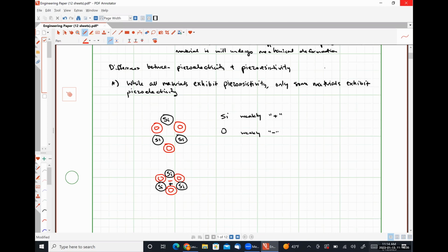Well, what happens when we have separation of charge? It creates an electric field, right? Which is exactly what we would expect in a piezoelectric material. Mechanical deformation results in the formation of an electric field oriented from the positive charge region to the negative charge region, right? So we're going to see some E field in the up direction when we compress this crystal. Now,